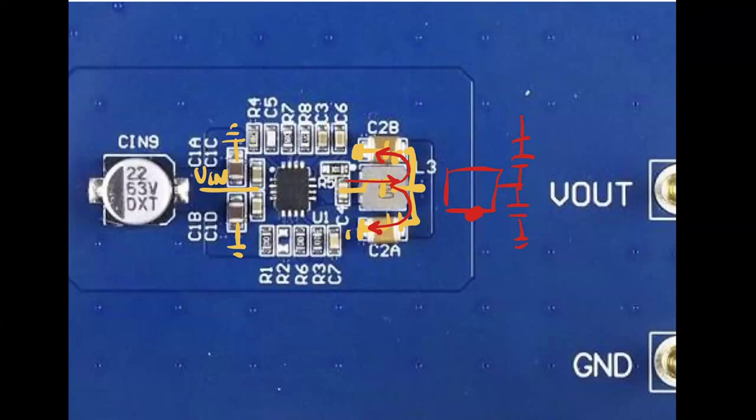Can I use one LISN box and do one conductor measurement at a time? Yes, you can. This is what you get when you buy a LISN with a switch. It's a switch in the front panel. So you switch from line to measure line, or to measure neutral, or to measure positive and to measure negative. The only disadvantage is that you will not be able to calculate differential mode and common mode. This is the only difference, because they will not be synchronized, and depending on your instrument, perhaps you only have the spectrum and not the phase. So you will not be able to add or subtract.